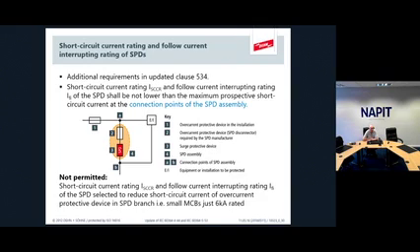The value of the breaker, or moulded case breaker or fuse, must be at least equal to the surge value of the SPD it's protecting. Otherwise, it's just not going to work.